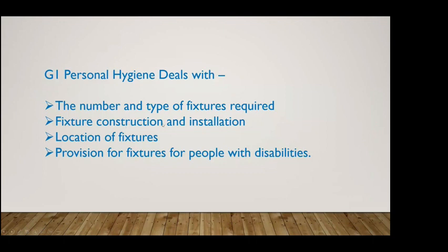What the fixture must be constructed to, in terms of minimums. So that's things like water seal depths in a toilet may be in there. Any other requirements, where they need to go, might be a requirement to have a door in between a toilet and another room, sort of thing. And specific requirements for disabled toilets. So there's quite a bit more space for them and stuff like that.